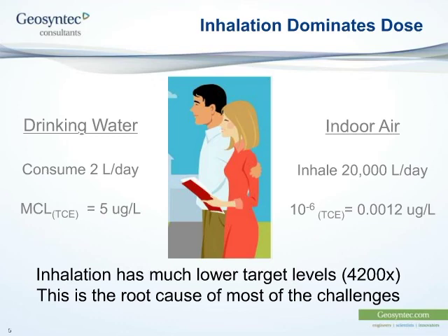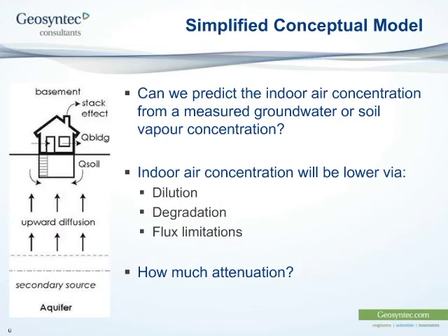We have such low target levels that oftentimes we're down in the range of background concentrations. We have to be very fastidious about cleanliness of sampling equipment to avoid carryover and sample contamination. And everything just gets more difficult when your target concentrations are that low.